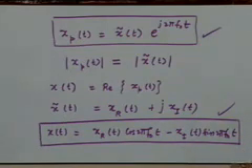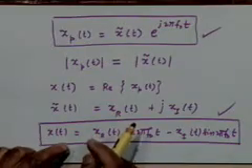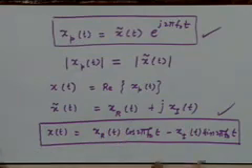A very significant result. For every band pass signal there is a corresponding low pass signal, in the sense that from that low pass signal I can generate the required band pass signal by a simple frequency translation operation. So which one is the band pass signal and which one is the low pass? You tell me. We started with what assumption about x(t)? x(t) was band pass. We have forgotten.